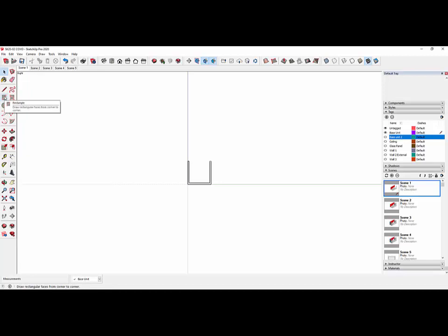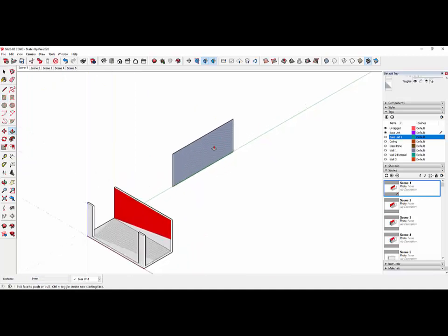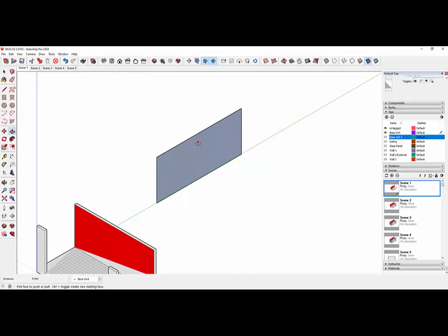So the process of creating a wall for the elevation: because we have this whole space to work in, let's make sure that we work away from the model itself. Let's draw a wall that's going to be somewhere in the region of 6,400 by 3,000. We'll use the rectangular tool to create it, and we'll type in the coordinates. I can go into 3D. Let's orbit, so we can type O, and we can extrude.